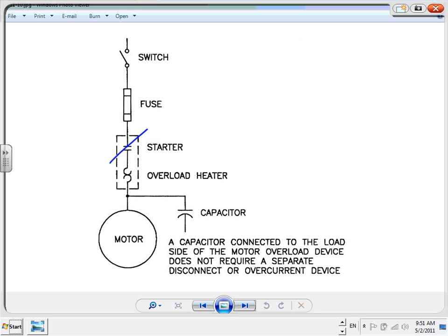You know what happens if you don't turn the capacitors off and your load goes down, like you shut down for whatever reason, the air handling unit went down? We shut it down, we don't need more here, but the capacitor stays on. You end up with a leading power factor higher than 100. They call it leading power factor. It means if you go to that receptacle here, you're supposed to get 120 volts, and now you're getting 150. High voltage.